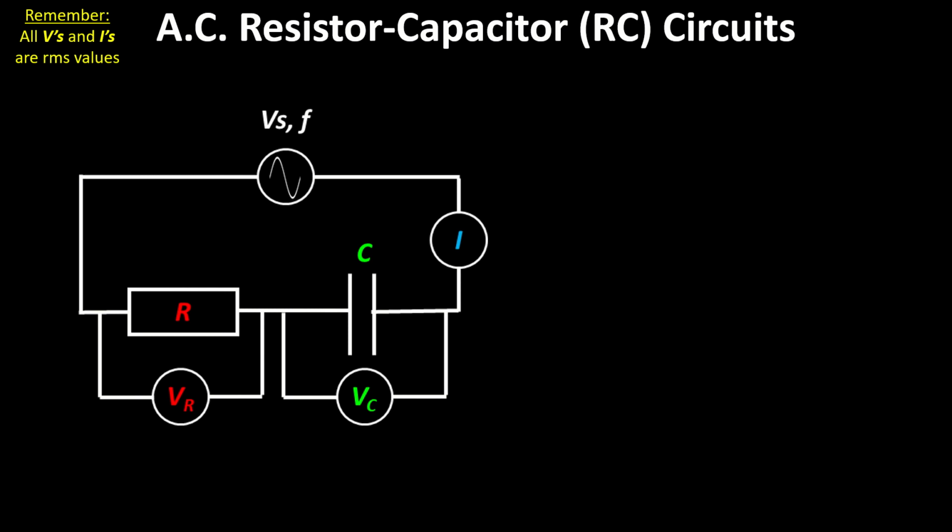You could use maximum values for everything as long as you use the same. If you had RMS values, they all have to be RMS. If you have maximum, they all have to be maximum. But we usually use RMS.